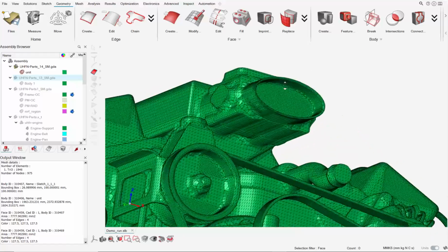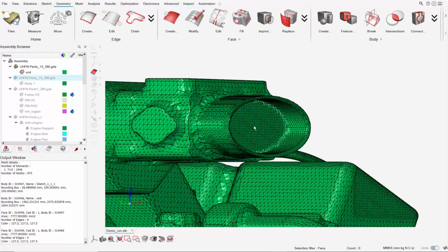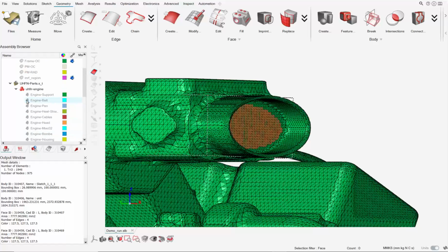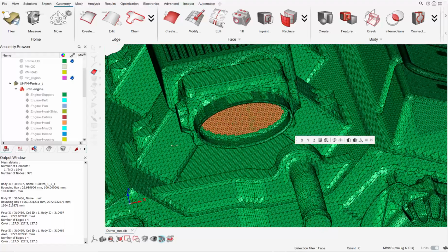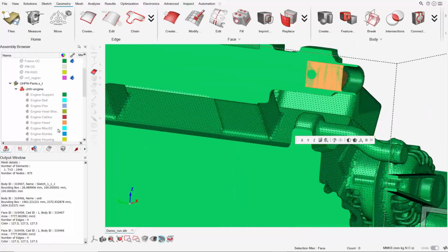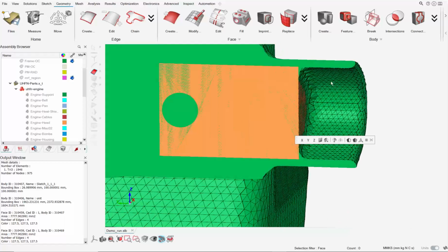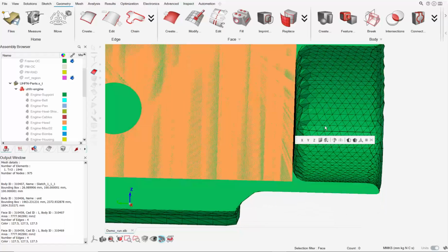We're gonna do the same thing for the engine intake. I'm gonna grab the intake. Put the section cut on the X normal direction. I will move it a little bit forward so that it sits flush with these elements.